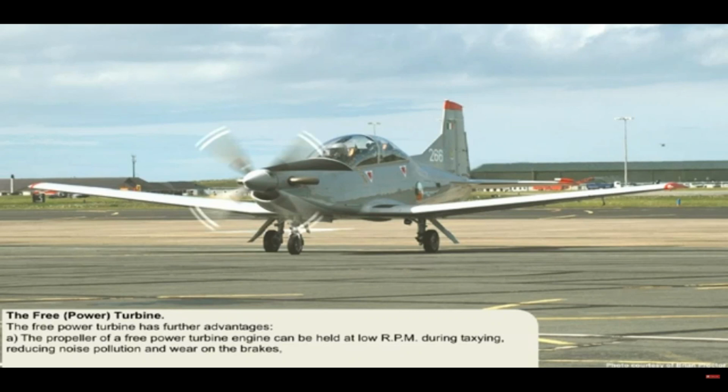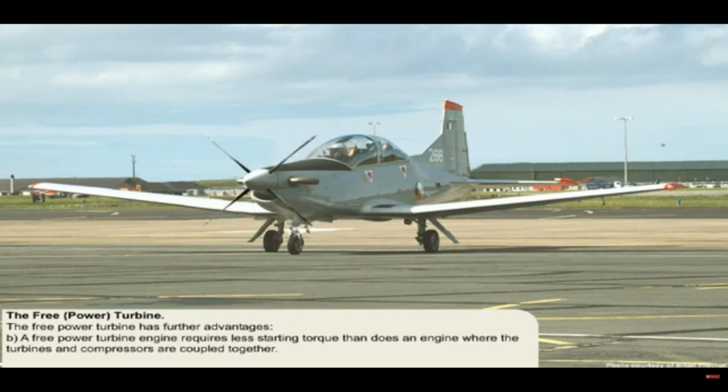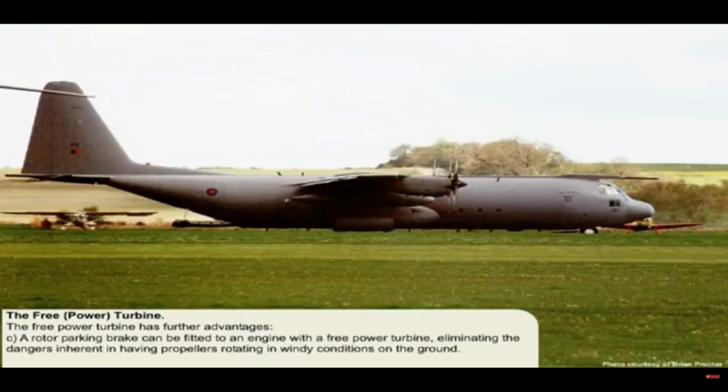A free power turbine engine requires less starting torque than an engine where the turbines and compressors are coupled together. A rotor parking brake can be fitted to an engine with a free power turbine. This eliminates the dangers inherent in having propellers rotating in windy conditions on the ground.